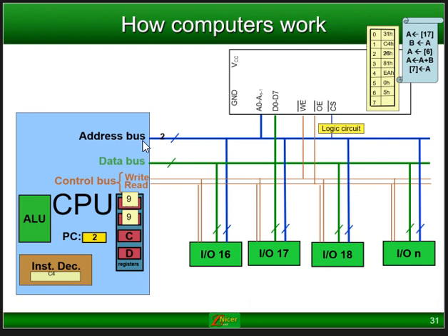And as you can see now, again, it's placed on the address bus. It's number 2. So we'll go to instruction number 2. That says go to address number 6, which is this one here, and load that into register A. Now in address 6 there's a value of 5 hex. So let's see what's going to happen. The instruction is first collected from that position, and then the instruction will be executed.